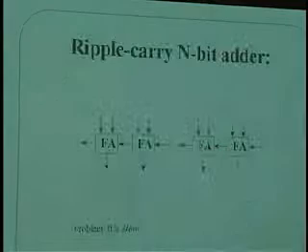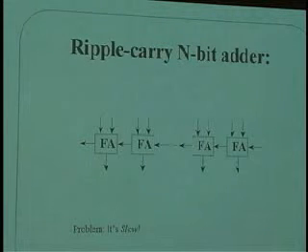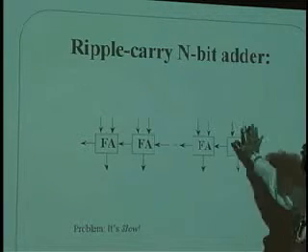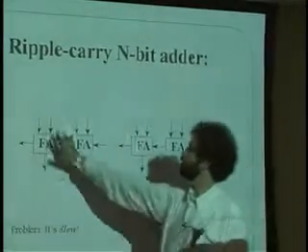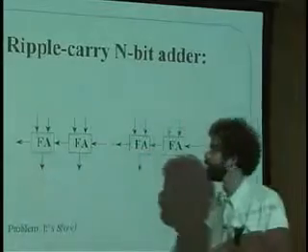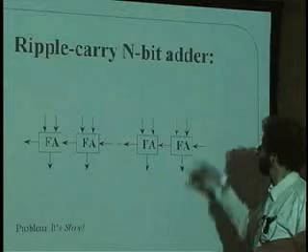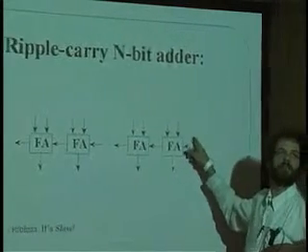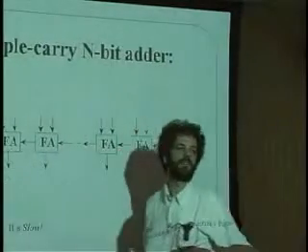Now, what you realize when you do this is that you could combine a set of full adders the same way that I just showed you there, by putting them in a chain like this, where the least significant bit is over here on the right-hand side, where we traditionally draw bit number 0. And the most significant bit is on the left-hand side over here. And if we're just summing together two n-bit strings, what carry-in do you think we should feed in on the right-hand side here? A 0 or a 1? 0. Okay, great.